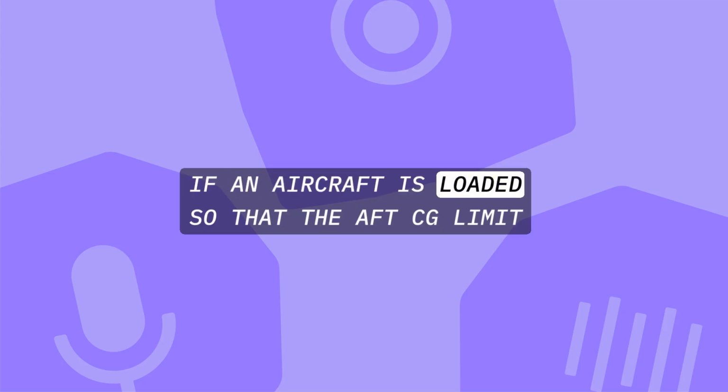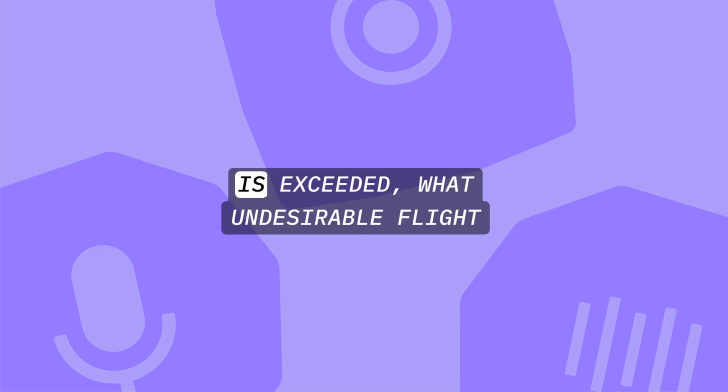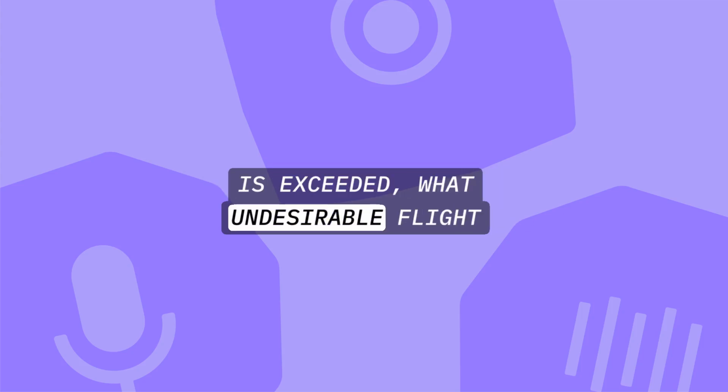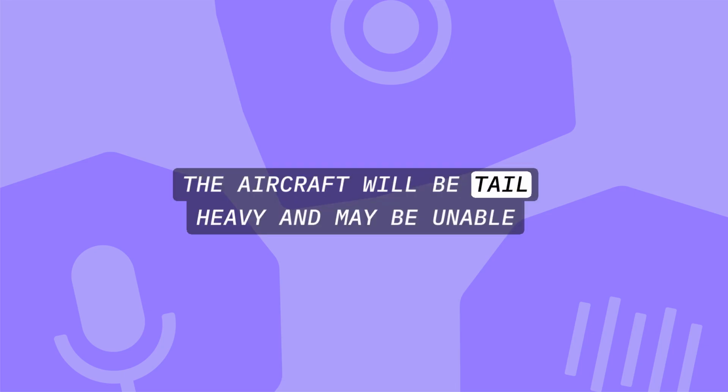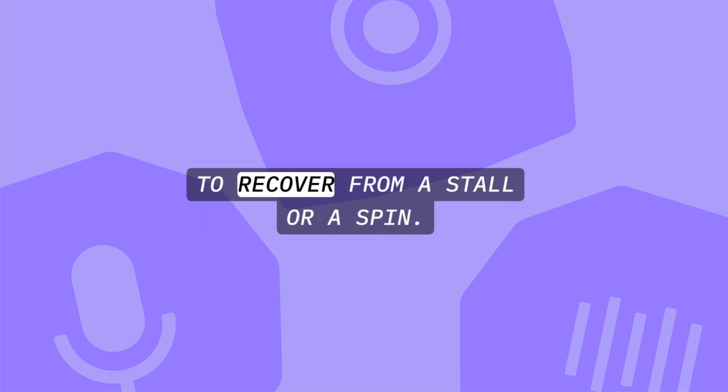If an aircraft is loaded so that the aft CG limit is exceeded, what undesirable flight characteristic is likely to result? The aircraft will be tail-heavy and may be unable to recover from a stall or a spin.